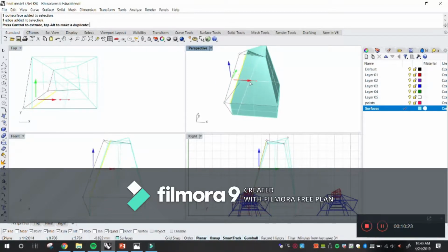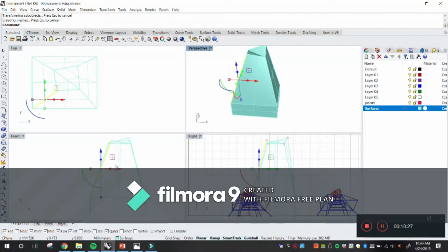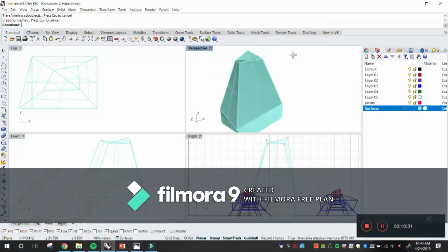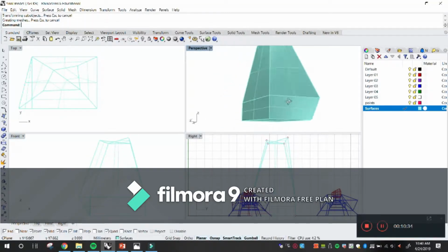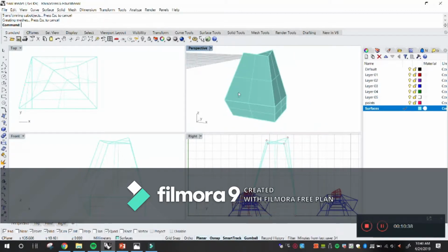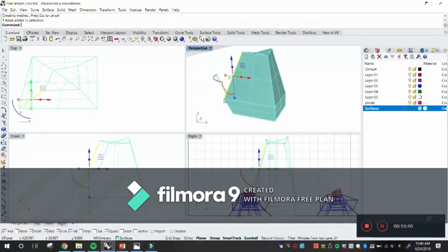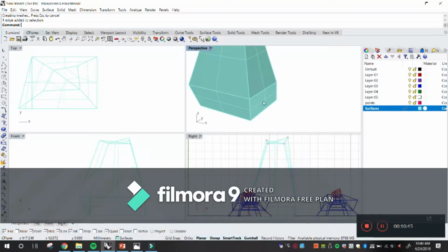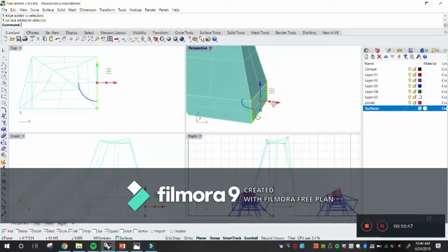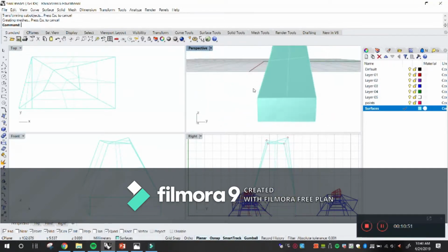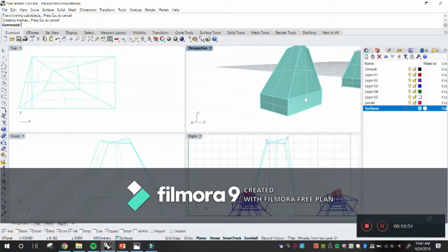And if you look on your bottom left corner, look what starts happening. You have 90-degree corners right here, but if I start moving some of that, I start getting some more dynamic forms. Now I can do that with vertices, which is Control Shift, select that, or I can actually do it with faces. So again, if I hold Control Shift and click, and then I pull this right here, I can pull that face out, which is sort of an extrusion.